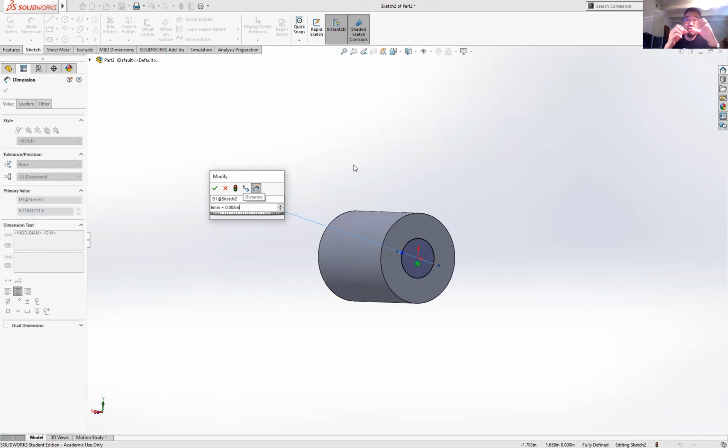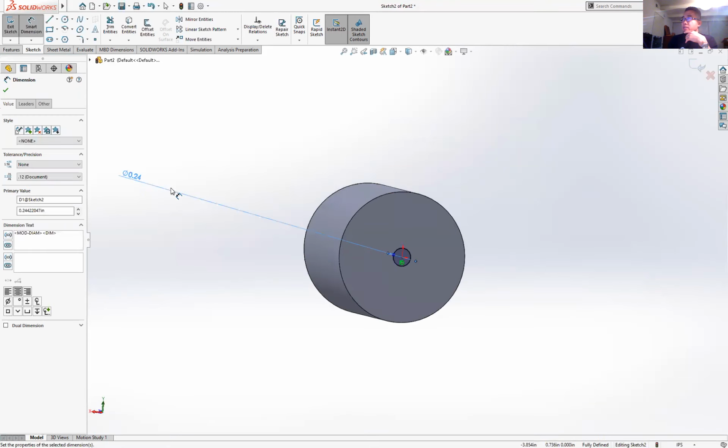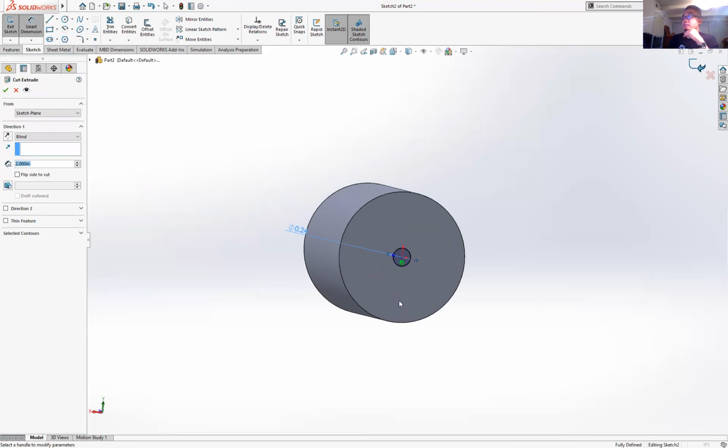The other thing you can do is just drill it undersized and then just drill the hole that you want right through if you have the right drill and a power drill. So, okay, 6 millimeters plus 0.008 inches, I hit check, and good. That seems about right. Okay, so you always want, when it does that smart dimension, you want to think in your head, did that go to a size that made sense? And sometimes you miss a 0 or a decimal and it doesn't, and so just be cognizant of that. Okay, so we're good. It's about 0.24 inches. Great. Okay. So I accept that.